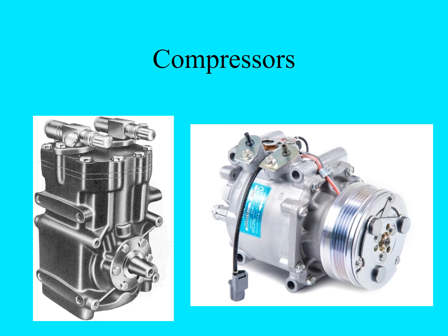The one on the right is a modern design. This could either be designed as a scroll compressor or a variable displacement wobble plate compressor or a piston compressor. They're all very similar. What's being shown on the front, this is the pulley and clutch assembly. The pulley is being driven by the serpentine belt.